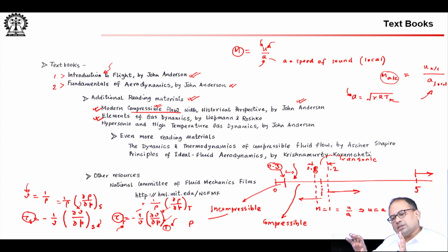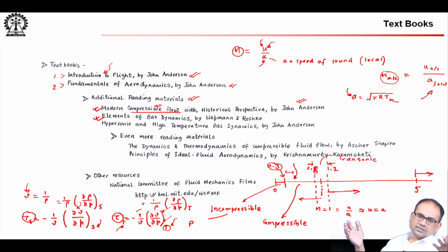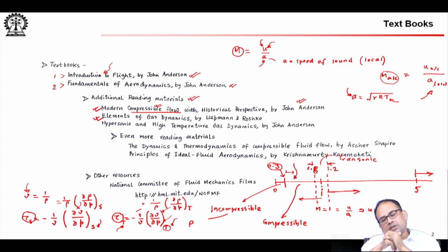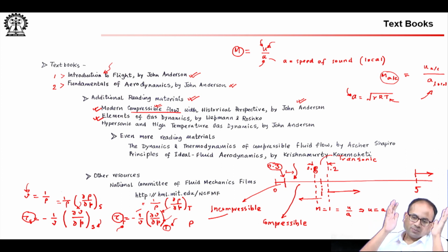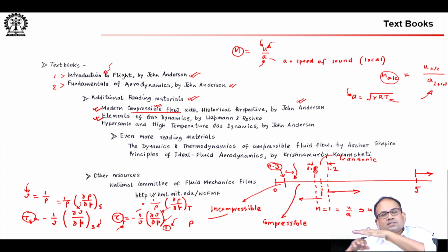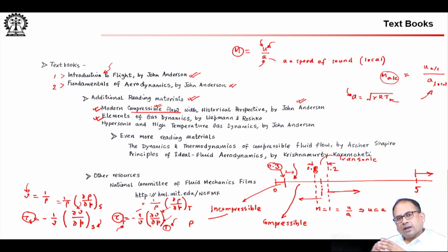Generally, flow in the engine is reduced to subsonic speeds or even to stagnation conditions, but in a scramjet engine, we will not get into the details, but because it is happening in aerodynamics right now, I still need to talk about it. In a scramjet engine that powers these hypersonic vehicles flying at Mach 6 plus, the flow in the engine is still supersonic, and to ignite, add fuel, and get thrust is a big challenge. That is also under the purview of aerodynamics. Of course, some chemistry and some thermodynamics is also there.